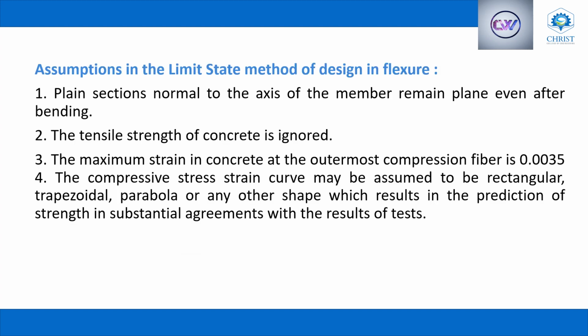Then we have to understand thoroughly the assumptions used in the limit state method. The first assumption is that plane sections normal to the axis of the member remain plane even after bending. It is the most common assumption, used in both Bernoulli's bending theory as well as in the limit state method. The second one is that the tensile strength of concrete is ignored.